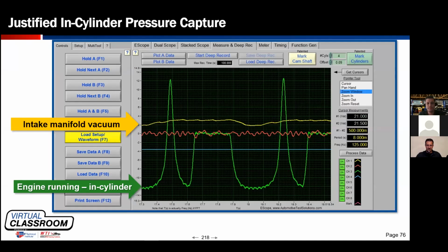Yep. That's perfect. And that's why this works so well, because when you have these confusing moments, we can't climb inside the engine and watch this happen, but you've got an engine right here. So you can say to yourself, I'm on the exhaust stroke, my exhaust valve remains open. I'm supposed to open my intake valve, but I can't, right?